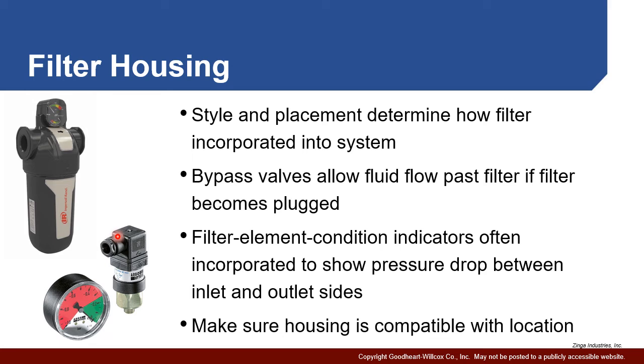It's also important to consider in terms of its location if the filter housing is going to work well. Is it made of the right materials? So for example, if you're in an external case, you might need a metal housing to make sure any type of, like, say, rocks or any type of debris might hit it. Temperatures might prevent you from using a plastic housing, etc. So you want to make sure that it survives well and works particularly well. You'll also notice in terms of the actual setup, generally these are mounted vertically with the filter hanging below.